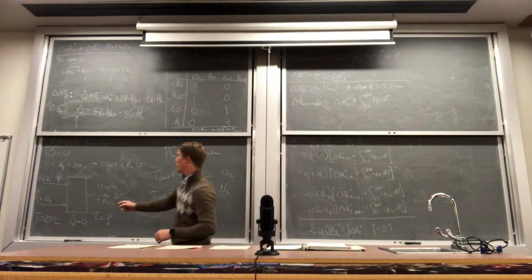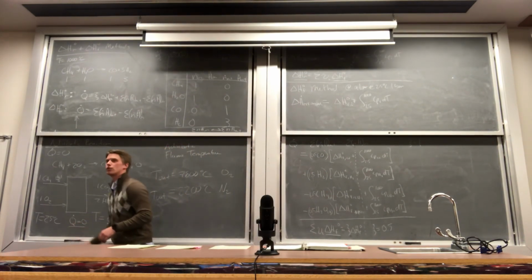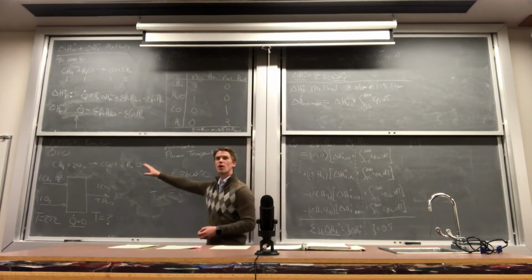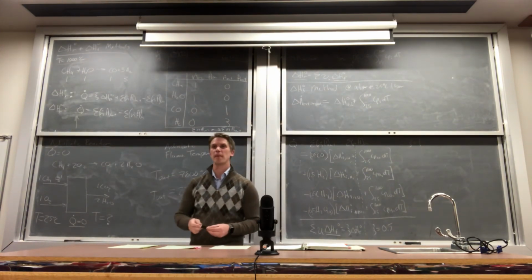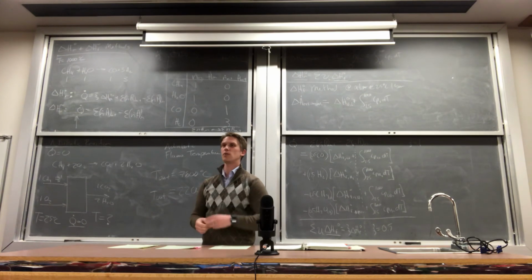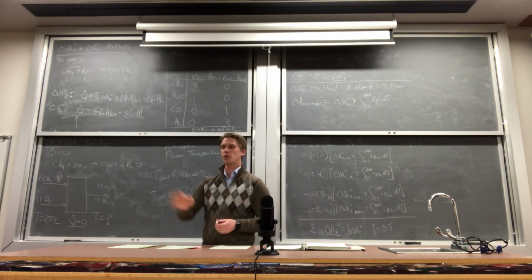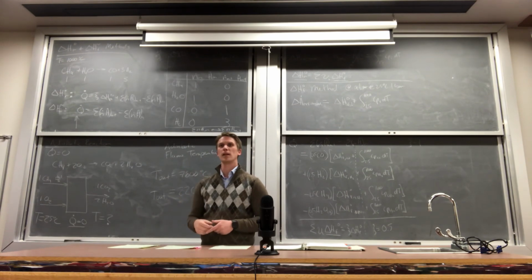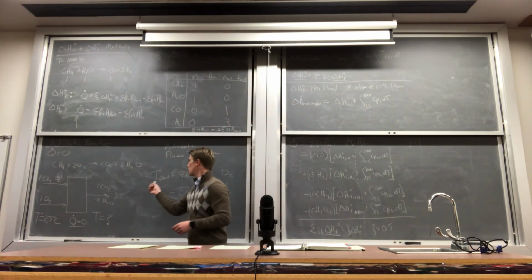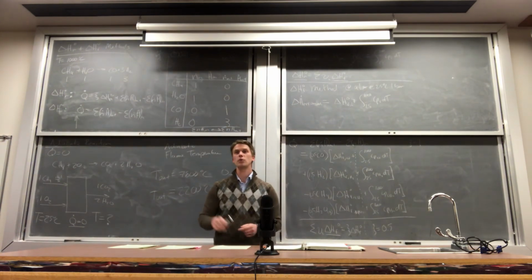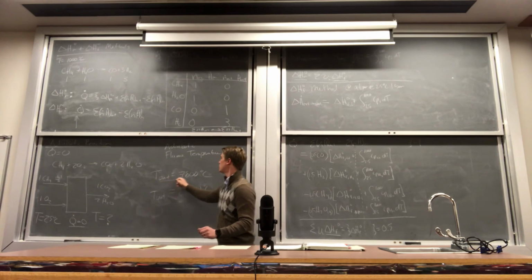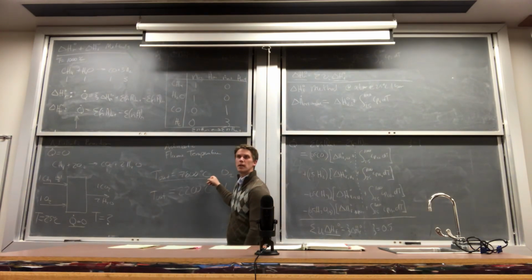So these are idealized calculations. So of course you are going to have heat transfer leaving the system extremely rapidly. When you have flames this hot, they're all going to be radiating energy massively. And that's most of the heat transfer that you deal with when you have a flame, like when you put your hand in front of a fireplace or the stove. A lot of the energy is being transferred by radiation. Of course, you're never going to get these temperatures exactly. But it gives you a good concept that if you were to burn your fuel in pure oxygen, that's how you get to a much higher temperature.